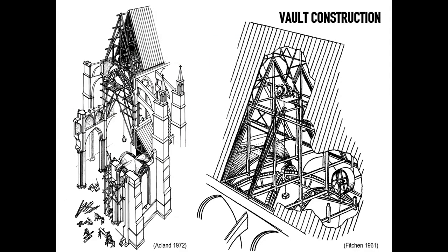So the vault construction is often what is mostly known about the Gothic cathedrals, but we saw already before how timber was an important ingredient of medieval construction. And certainly the roof of a cathedral was arguably built first, before the cathedral. You can imagine that the builders understood the concept of locking out the building to protect the works from the weather, and then finishing off these intricate and very complex pointed vaults from inside, by using the structure of the roof itself as a temporary platform from which to locate treadmills for lifting up works, and possibly also to suspend some temporary scaffolds.